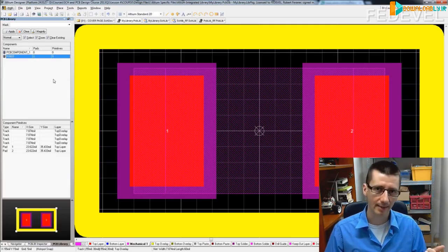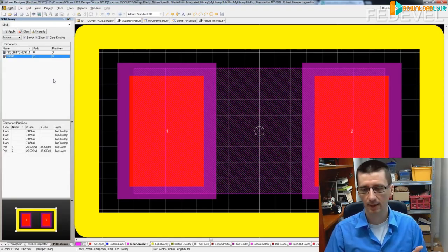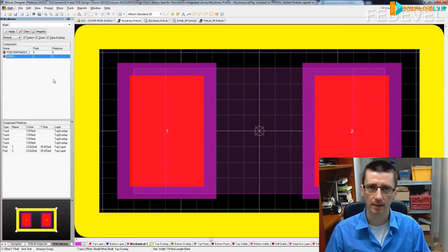I can use a black 3D model for resistors and a yellow 3D model for capacitors, so the board looks more real. The second thing is there is a little bit of difference between capacitor and resistor footprints, because capacitors are taller, so they need a bigger pad than resistors.